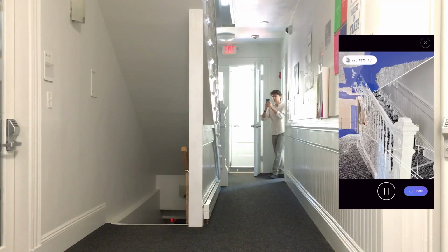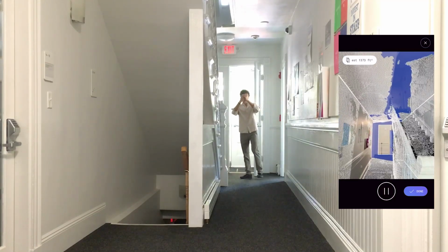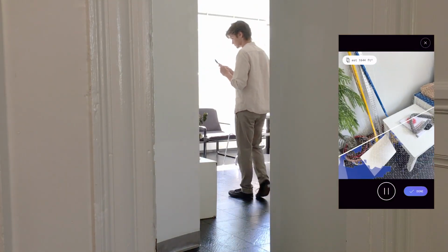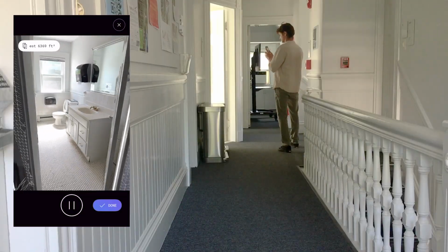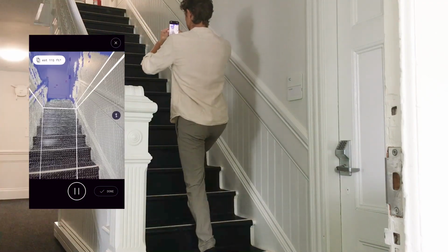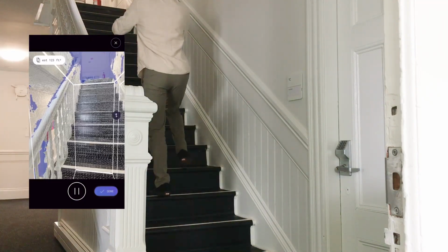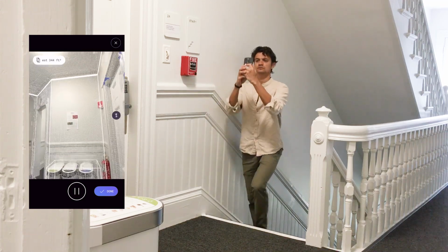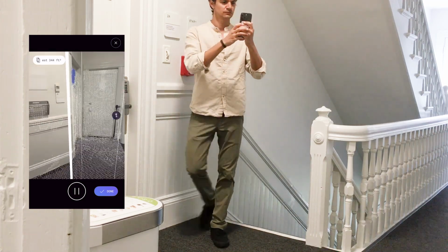A good rule of thumb is to take 2 minutes per 100 square feet. This residential unit is about 1,500 square feet, so I'm going to take about 30 minutes to capture it really well. It is possible to race through and capture it in a quarter of that time, if accuracy and completeness aren't important, but taking a few extra minutes now can save hours or days later on in the process when you don't have to return to the site because you took the time to get a more accurate scan.